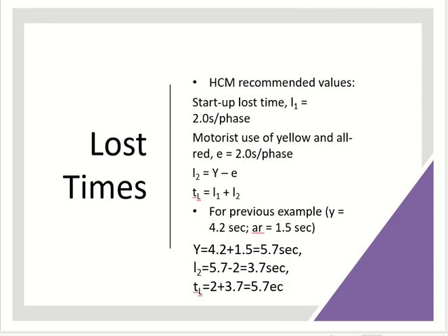For the startup, the loss time is 2 seconds per phase. Startup is when the signal becomes green. The loss time when the signal becomes green, while the driver is still getting ready. Just keep one thing in mind: when we say 2 seconds per phase, it is not per driver. If there are 3 drivers, it's not 2 seconds and 2 seconds and 2 seconds.